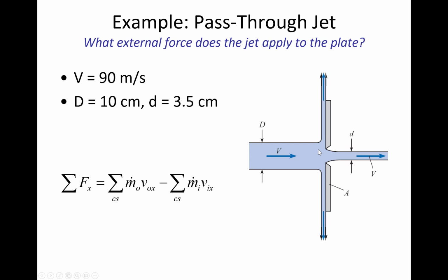And so what the orifice is really doing is that some of the stream that was moving horizontally is now moving vertically. What we're looking at is a cross-sectional view, so it's not like there's two outflows. It's kind of like fanning out. It was a circle jet, and then it's spraying in all directions this portion that couldn't fit through the orifice. Big D is before the jet passed through the orifice, and then the little d, 3.5 centimeters, is the diameter of the outflow jet.